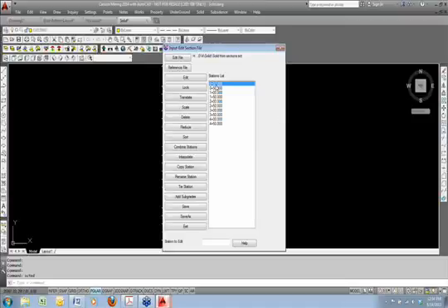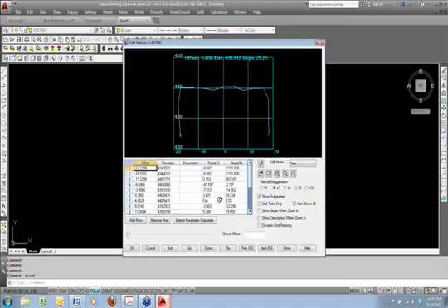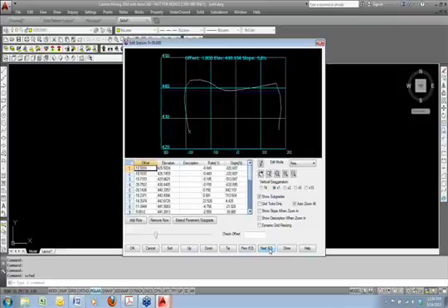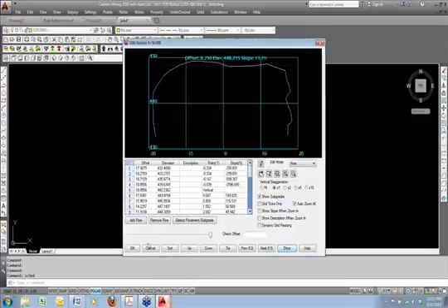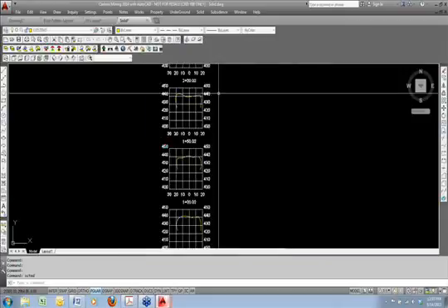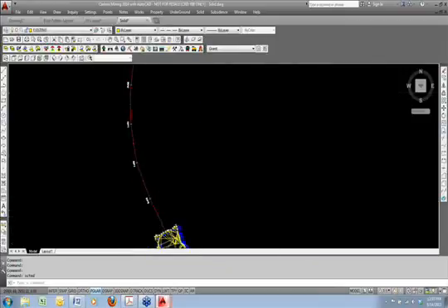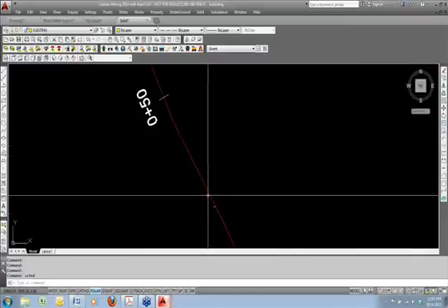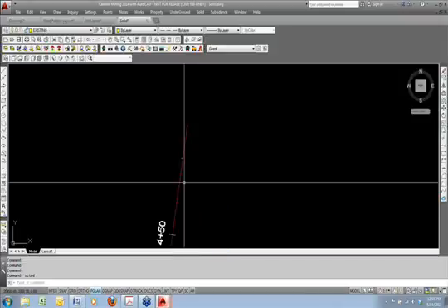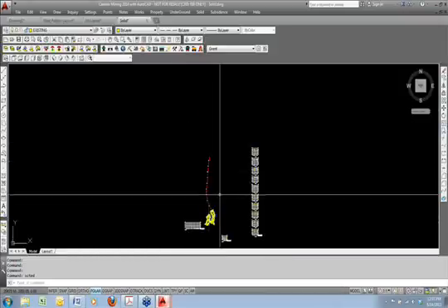There's station 0 to 4500, and I'll just go next all the way through it. You can see now the sides are not vertical. It does handle the overhangs, the circular cavities. That's not a problem. And so I've made these cross sections, just an SCT file. Okay, exit. And it also needs the alignment. So I just drew a center line attached to the end of that previous solid. Stationed it so those cross sections should go all the way up to 4450.